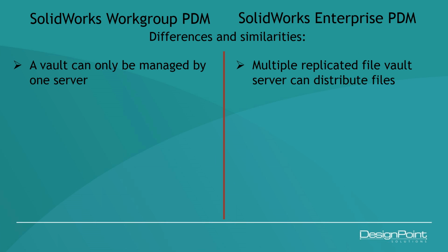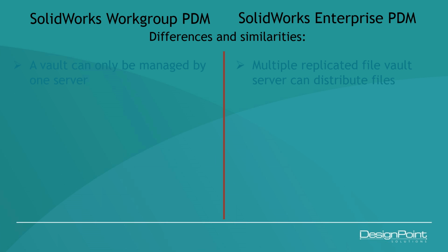In Workgroup PDM, a vault can only be managed by one server, so you cannot have replication. With Enterprise PDM, you can have multiple sites and replicate information to multiple servers, which makes data transfer easier, and the users will not have any performance issues.